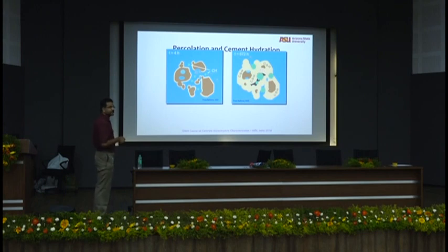What happens after 672 hours, and that's what, 14 days, 24 times, no, 28 days. 672 hours is 28 days. After 28 days, see what happens? Lot of CSH, some unhydrated cement, there are some voids inside, there is calcium hydroxide, there is gypsum. Now, is the solid percolated completely? Of course you can consider this to be water around, but in this solid, the solid is connecting itself completely, right?